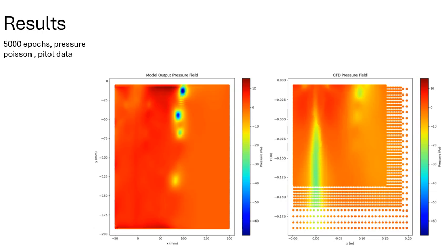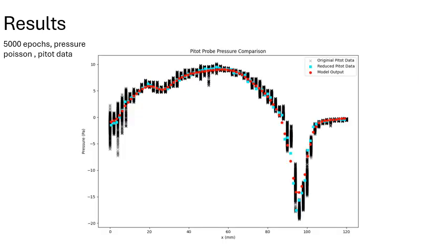That's because for our PIV data, we only have X and Y components of velocity. There's no out-of-page components of velocity. So we're missing that center vortex that's shedding from the propeller that the CFD captures. We do get those tip vortices here, here, and here, which is awesome. But the magnitudes are also a little bit different. Some reasons that this may happen come from the next slide.